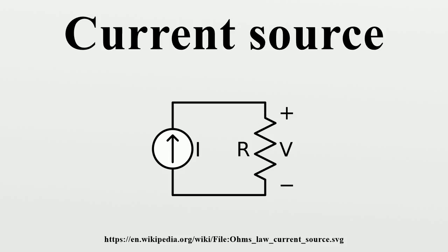This creates a negative feedback loop within the circuit, which keeps the voltage at Q1's emitter almost exactly equal to the VBE drop of Q2. Since Q2 is dissipating very little power compared to Q1, Q2 will not heat up any significant amount and the reference voltage across R_sense will remain rock steady at about 0.6 V, or 1 diode drop above ground. Regardless of the thermal changes in the VBE drop of Q1, the circuit is still sensitive to changes in the ambient temperature in which the device operates, as the VBE voltage drop in Q2 varies slightly with temperature.